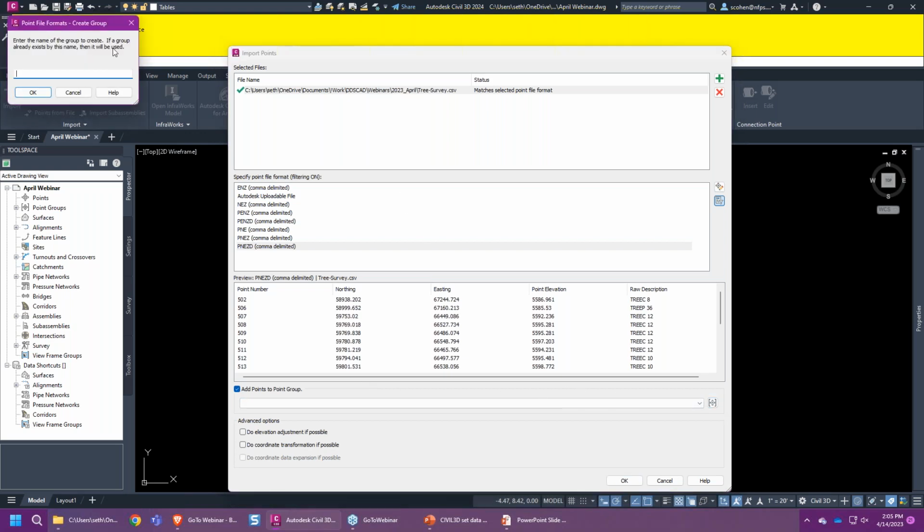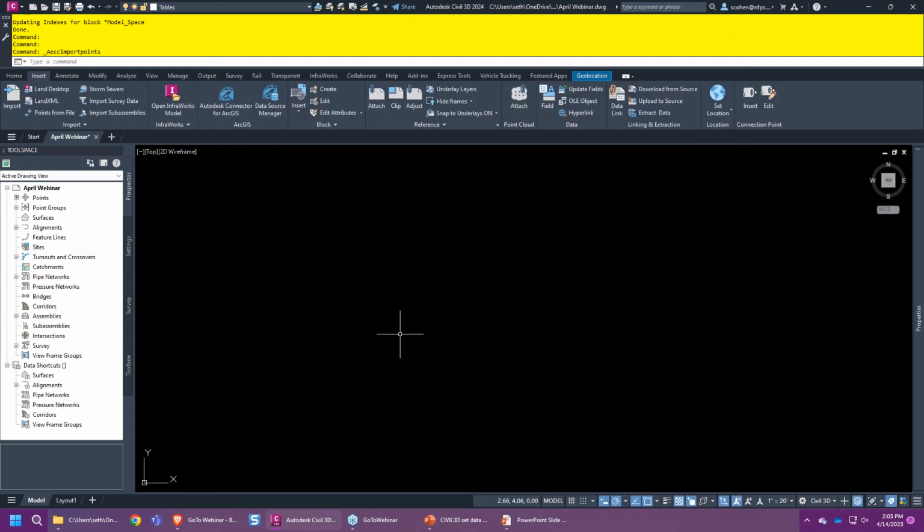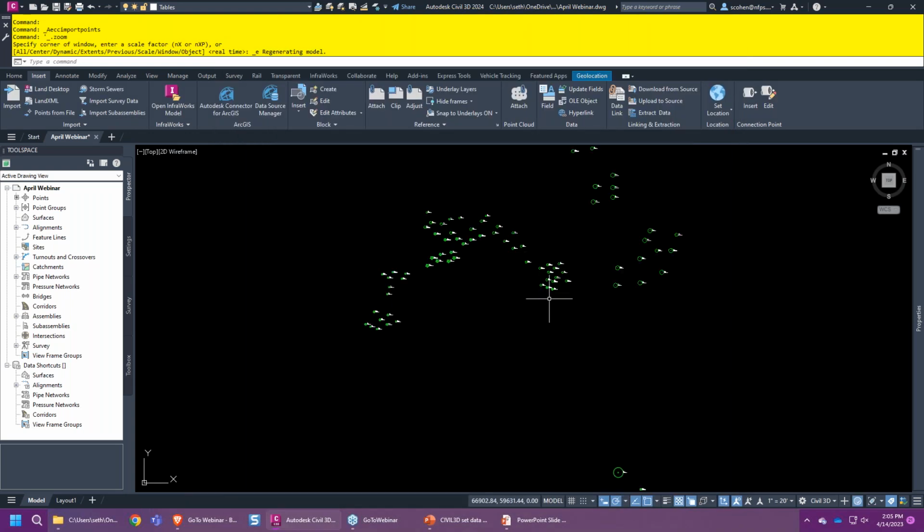So I'll go ahead and just call this from survey. So it's not survey, spell that right. All right, and then click OK. And I'll just go ahead and make sure I pick the right one. I always make sure we get the right one, PNAZD, delimited, and we are good to go. And I'll do a zoom extents, and there are my points.